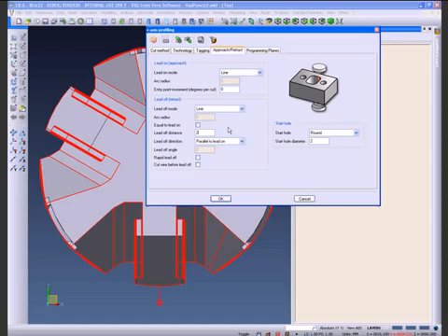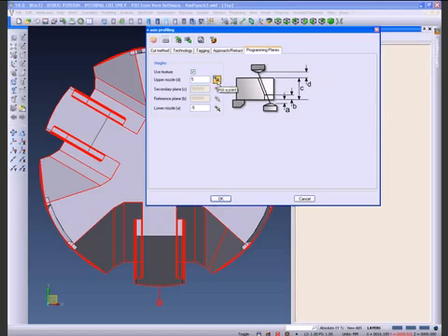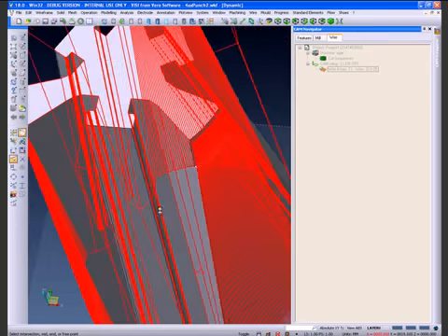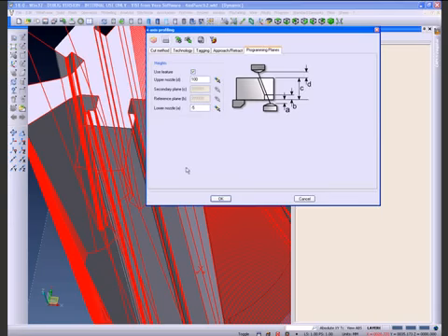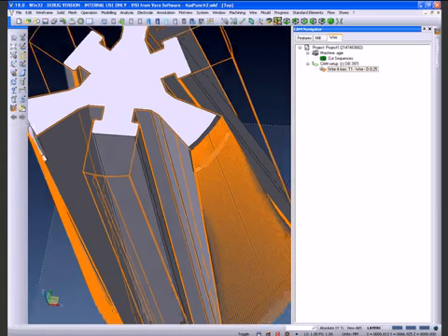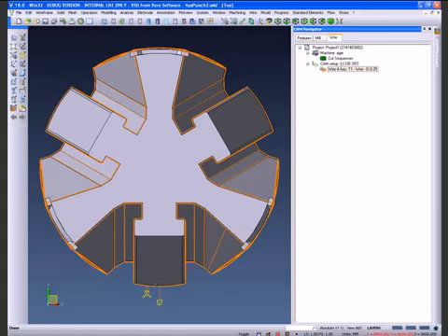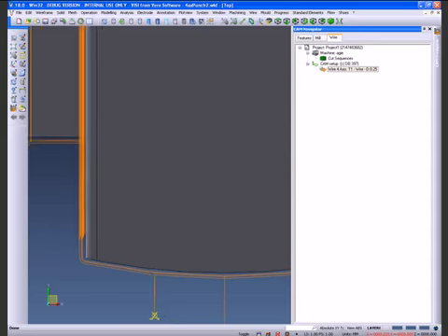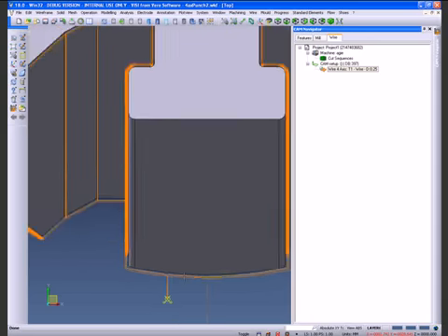Now the tagging details have been entered, let's have a look at changing the top and bottom nozzle heights. We can do this by actually snapping onto geometry in the model itself to give us the highest point of the model. This shows at 100 mm, so if we just add an extra 5 onto that and obviously put in -5 to give us the bottom edge for the simulation. We now have a new 4-axis toolpath with the tagging options applied as we determined.